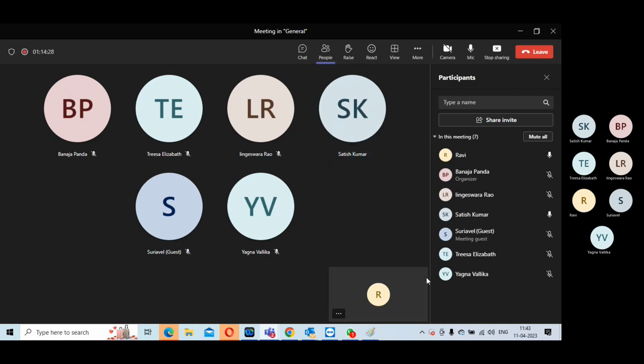Okay, so then it is correct. It will be in the LEF side. All the cells present in LEF should be present in lib, present in GDS, present everywhere, but what information is present in each of them is what differs. Physical-only definition will be present in LEF. LEF is only an abstract version. Yes, LEF is not used by any of your actual tape-out layers, it's GDS. You don't want to carry all the silicon layers, that's why you create an abstraction in the form of LEF, the library exchange format.